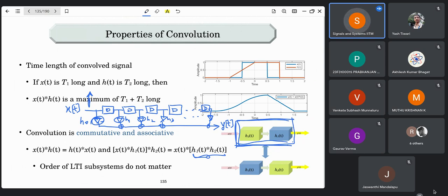That is because it has memory. Yes. Think of it even simpler: you have a sequence of flip-flops. You just feed in one bit and then take off your input. Think of this as a linear shift register where this one bit keeps moving from one flip-flop to the next flip-flop at every clock cycle. You'll still keep getting an output, right? Like a counter. Yeah, correct. Good.